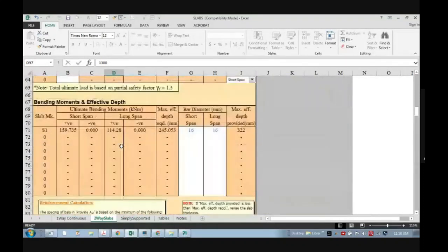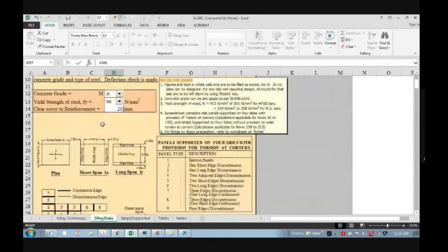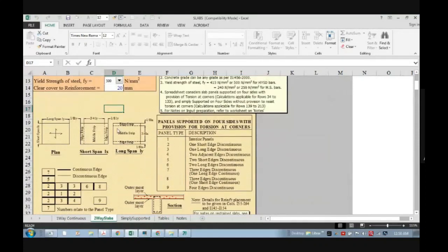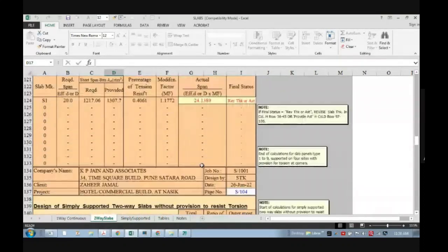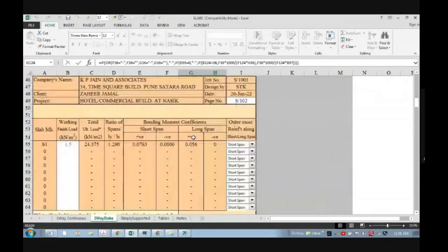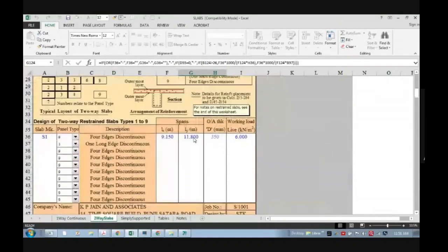Yes, you can increase fck, but that will not give you much difference. अभी बड़े स्लैब रहेंगे तो 30-25 तो लेना ही चाहिए कम से कम. But if it is at the boundary, it will help. Otherwise, generally, changing the thickness is always a really good choice. It helps you for serviceability and even for steel percentage and strength and all.